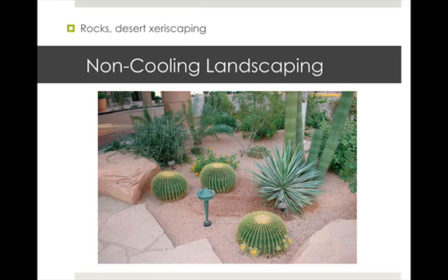The absorbency of the landscaping will determine how much heat is reflected from the land to the structure. A rocky landscaping in a hot climate, like you see here, will heat the nearby structure, whereas grass will help cool it by absorbing solar radiation and cooling the air via evaporation.